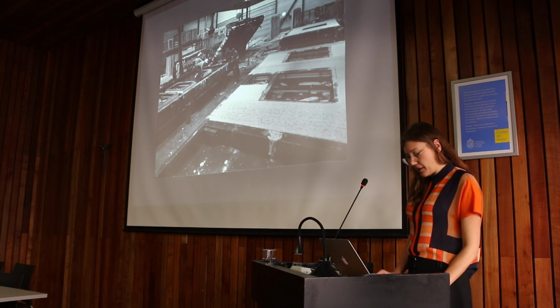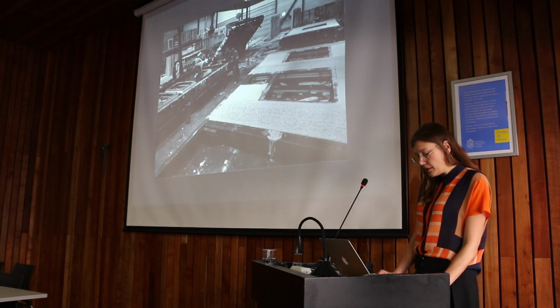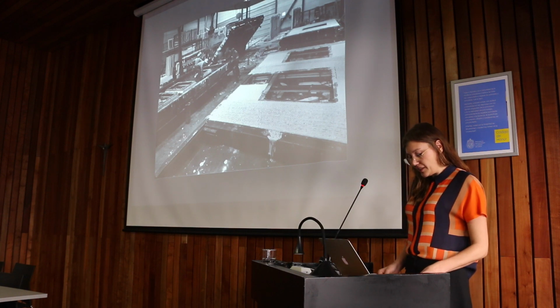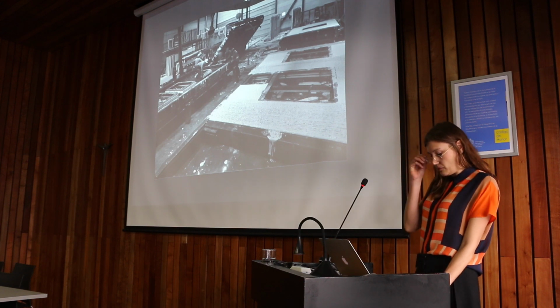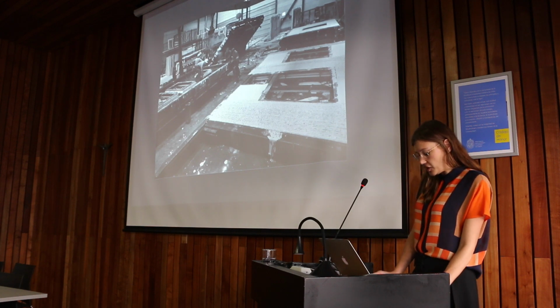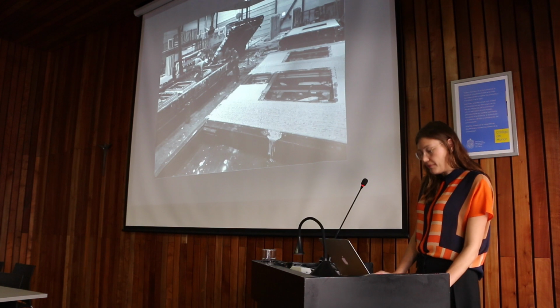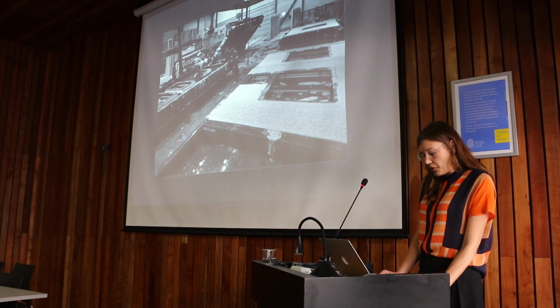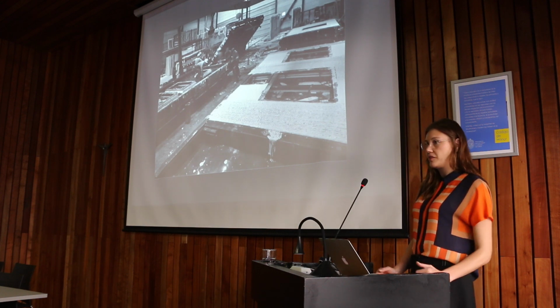Even in the most efficient production line, the preparation of the mold remains the most time-consuming and labor-intensive part of the manufacturing process. Consequently, the building industry has developed various ways of making formwork construction more efficient. By simplifying shapes and employing orthogonal geometries, shuttering can be constructed out of large surface materials for quicker assembly. For this reason, concrete columns are frequently square in profile, although a circular profile is more ideal because the flexural strength would be the same in all directions.